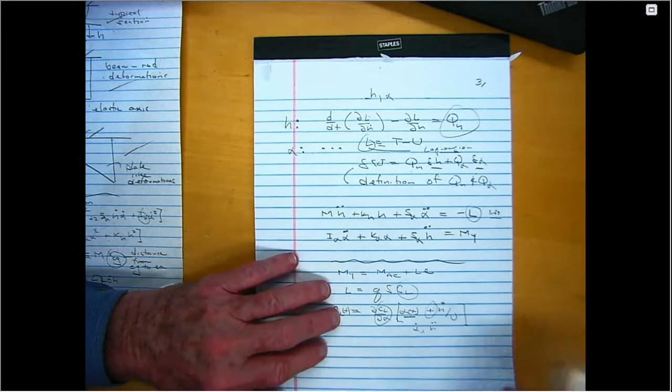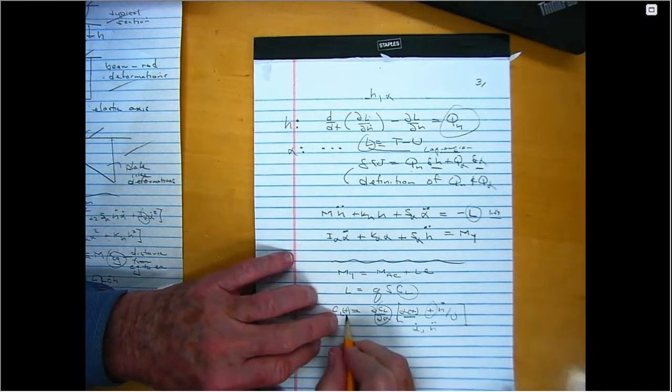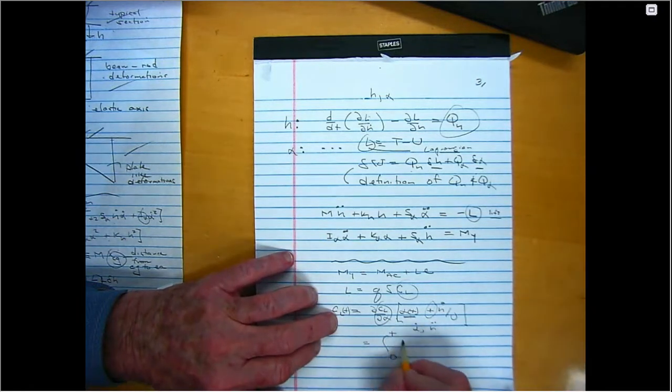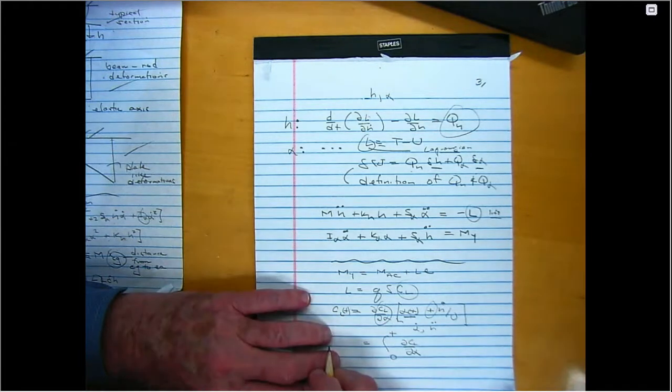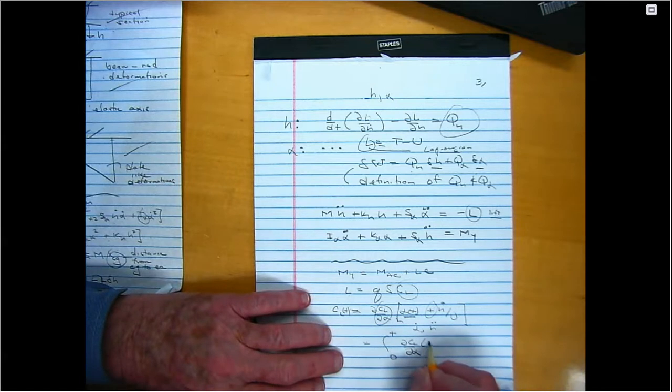But now, appropriate to your question, there's another possibility, and that is that the C_L at the present time depends on the integral from 0, whenever the motion began, up to the present time. Now dC_L d alpha, which is no longer a constant, depends on time. And so I write this as a function of t minus tau, times alpha of tau, d tau.